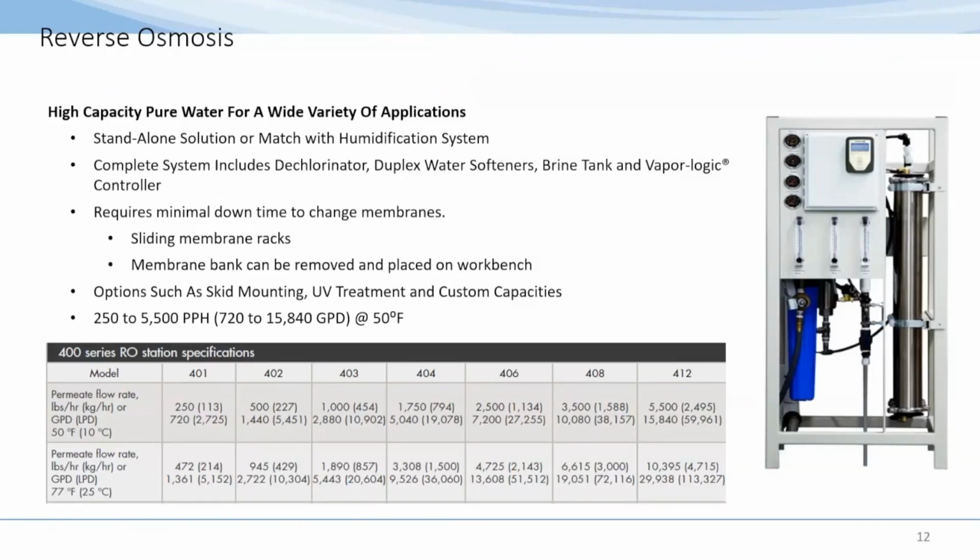This is something where we're essentially taking out calcium and magnesium, something that's vital to the plant growth, and adding in additional sodium, and the potential risk of an improperly operating system would also give additional chloride, which could be detrimental to plant growth.